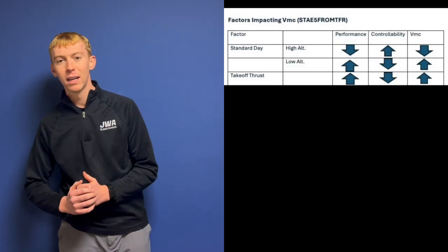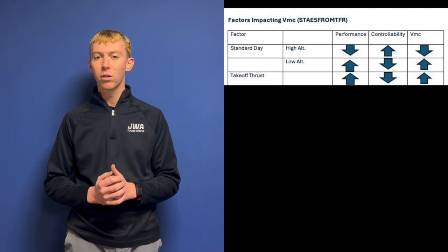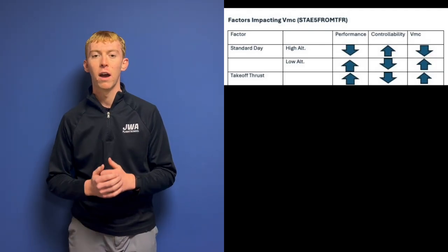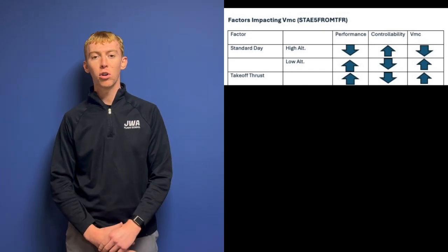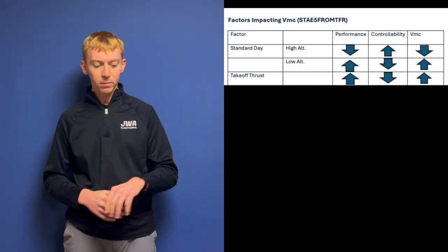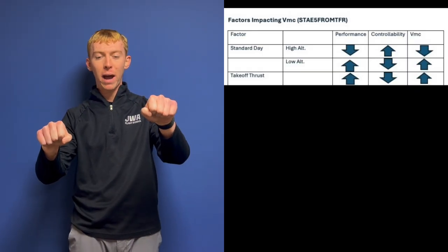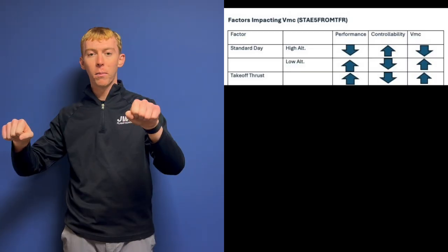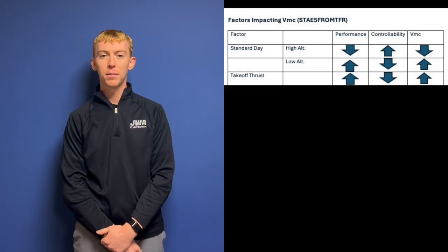Our next topic is takeoff thrust. Takeoff thrust is going to increase our performance. We have more thrust, we have more power, we have more performance. Controllability, however, is going to decrease. If I have my left engine and my right engine, and my left engine's at full power, it's going to yaw the airplane quite a bit more, therefore making the airplane less controllable. VMC is going to increase at takeoff thrust.